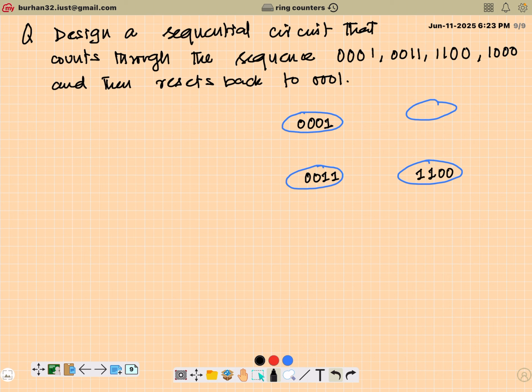So there will be no external outputs. There will be only state inputs and state outputs, and there will be 4 of them. So this will be the initial state, and these will be the transitions. When you create the standard architecture, although again there are 4 states, as in when we designed that ring counter, it is explicitly mentioned that these 4 states need to have this count. So when you go for a standard architecture, it will have a 4-bit state register that will generate 4 state inputs S3, S2, S1, S0, and 4 next state outputs N3, N2, N1, N0. And the rest of the steps will follow.